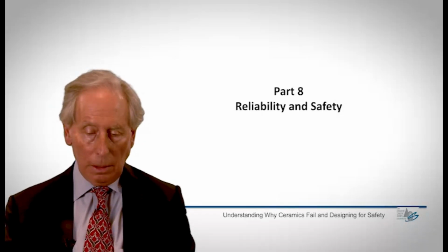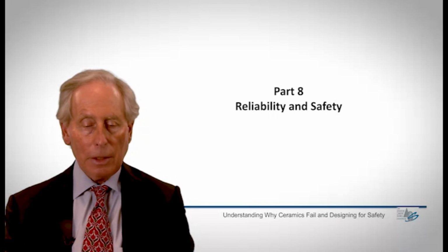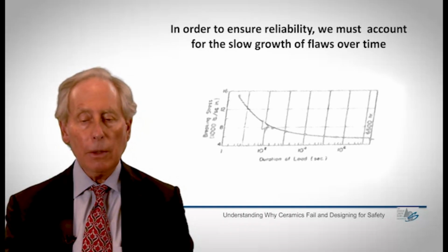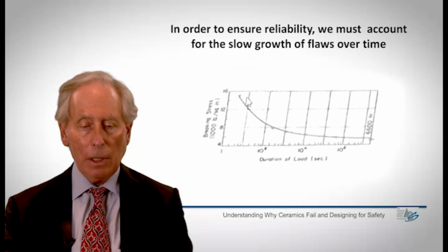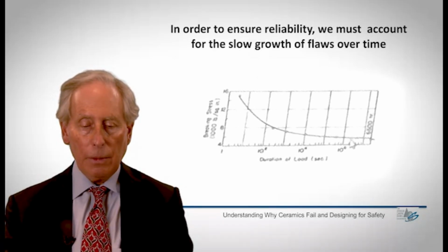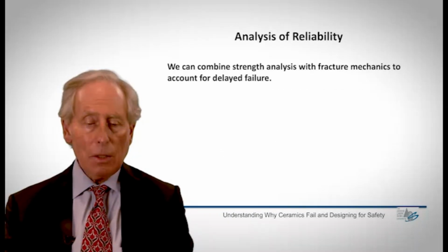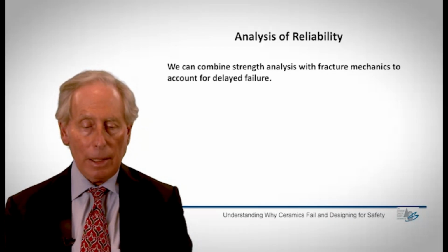So first of all, just as a reminder, I showed that cracks can grow slowly with time, which means that our measured strength decreases with time. This is important. I can't always design with the highest strength. I have to know what will happen after long periods of time. So we can combine strength analysis with fracture mechanics to account for delayed failure.